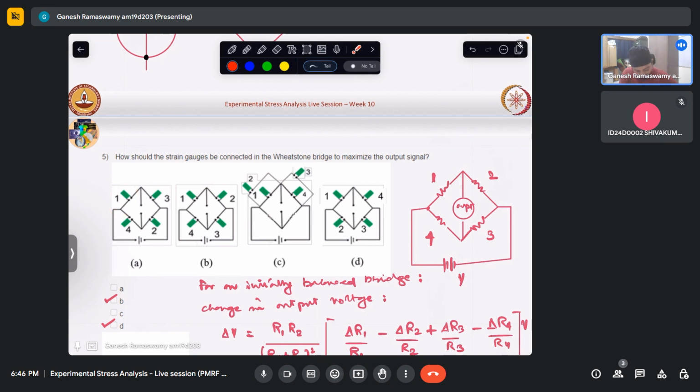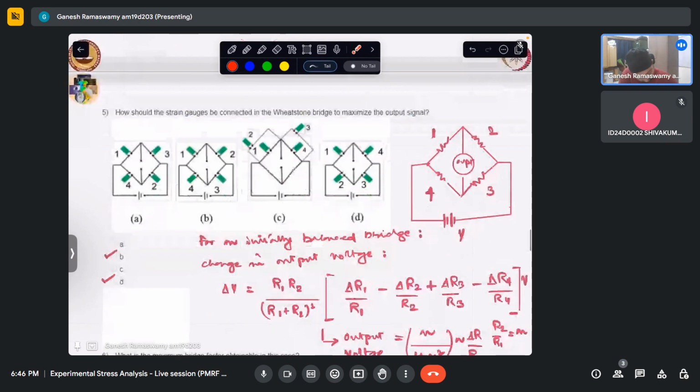That is why we would generally not go for two taps, but for three taps, which is something called temperature compensation, which we will look at in the next session, as to how we can get over temperature effects by suitably tweaking our Wheatstone bridge arrangement by having a tap that has three wires instead of two, just for a quarter bridge arrangement. So I hope this is clear.